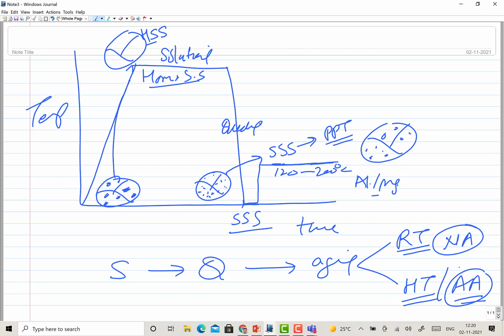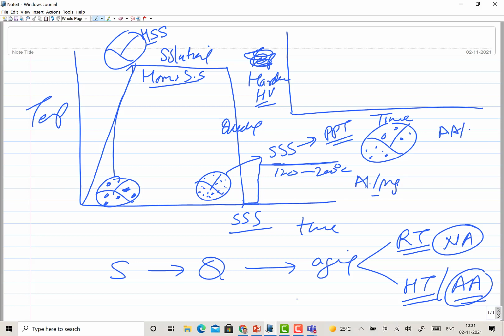Okay, so how do things change as a function of the temperature during the heat treatment. Here we have time, and here we have temperature as far as aging is concerned. If we give very high temperature exposure, here we have the hardness, the way the strength will be changing as a function of time during the aging. Okay, variation in hardness, say HV, as a function of aging time, which may be artificial aging or natural aging. So we'll talk about the artificial aging particularly.